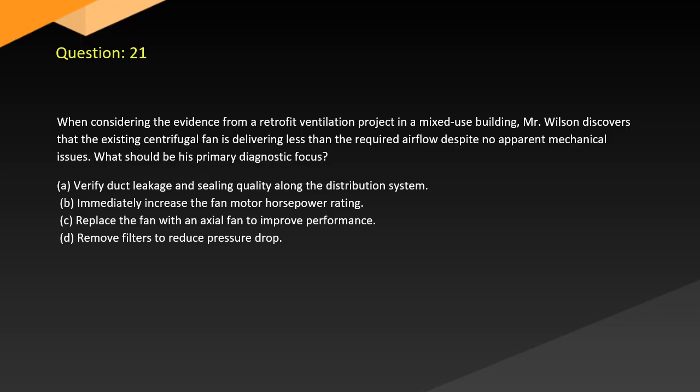Question 21. When considering the evidence from a retrofit ventilation project in a mixed-use building, Mr. Wilson discovers that the existing centrifugal fan is delivering less than the required airflow despite no apparent mechanical issues. What should be his primary diagnostic focus? A. Verify duct leakage and sealing quality along the distribution system. B. Immediately increase the fan motor horsepower rating. C. Replace the fan with an axial fan to improve performance. D. Remove filters to reduce pressure drop.